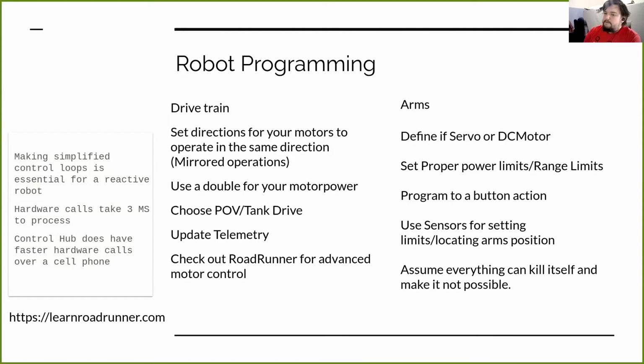I would recommend making an arm's movement as simple for your drive team as possible, meaning make it a single button, make it an iterational step. So like you have your D-pad, you want to take an arm up, have it be, all right, I press right trigger, or I hit the A button, whatever it might be, and it goes to X height.